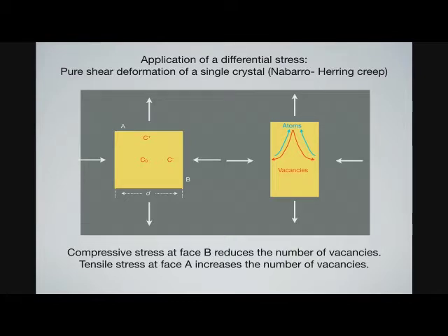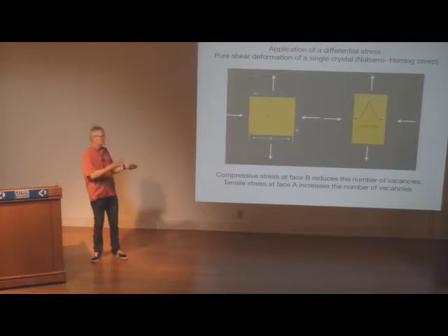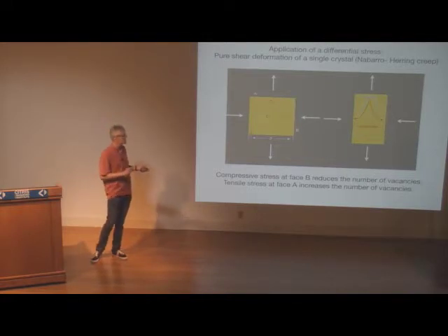If you put all of this together and keep creeping it in your dead weight experiment, eventually you change the shape of this material, right? You start from a square or a right cylinder, and as you flow long enough, through the diffusion of vacancies and counterflux of atoms, you eventually change the shape of this material, right? Really the idea is that your non-hydrostatic stress changes defect concentration.